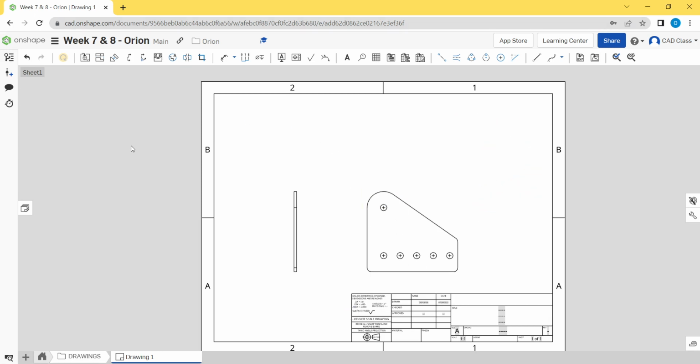There's also a section view. A section view doesn't have a ton of utility for a part like this, but if there's some part where I need to show a more detailed view of a cross section, or if I'm doing a drawing for a complicated assembly, maybe I want a section view that cuts the part in half and looks at the end of one of the sections.